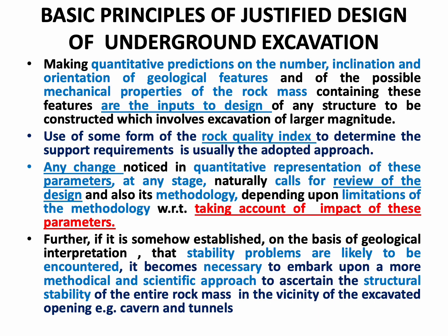So, the basic principles of a justified design of underground excavation would be about making quantitative predictions on the number, inclination, and orientation of geological features and of the possible mechanical properties of the rock mass containing these features. These are thus the inputs to the design of any structure to be constructed which involves excavation of larger magnitude. So now we are talking of basic principles of justified design for large underground excavations.